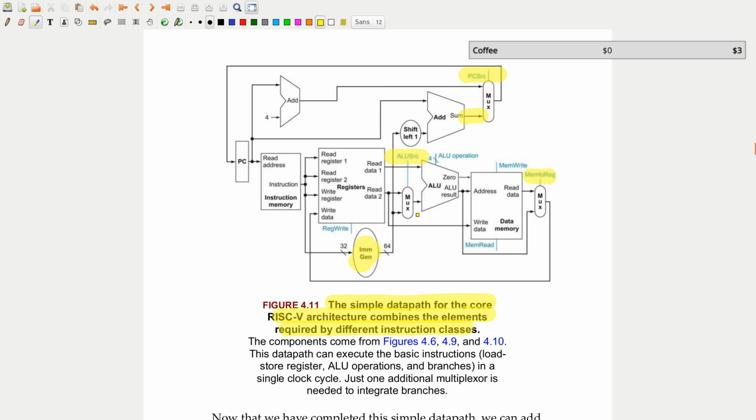And so we've built a fairly simple processor. And so for all intents and purposes, this is a simple processor. It's what we call a single cycle processor. We don't have any buffers in here or anything to split up the instruction across multiple clock cycles. Simply, the program counter gives some value and all of our inputs trickle through this entire pipeline all at once.